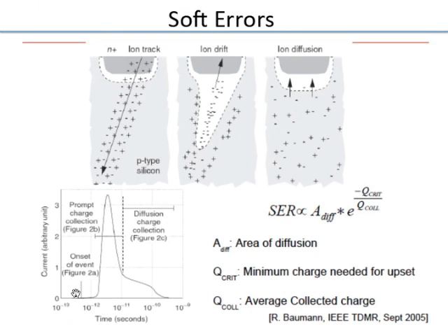The way this works is, when you have the ion go through, you suddenly have a burst of charge created. And remember, what we are showing here is the diode, the source and drain diffusion region. We are just looking at that region. So you have this burst of charge created, and then the electric field pulls in and separates out the charges, and then eventually some leftover charge drifts and diffuses because of concentration gradient. So if you look at the current profiles, there is a peak of current, and then slowly the current decays. And this will lead to an error.